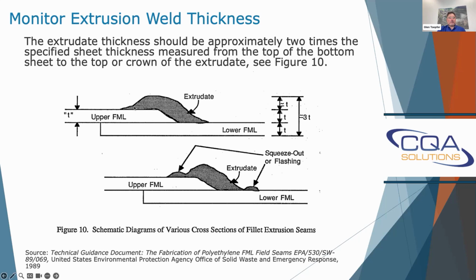A lot of times you get installers and they're lumping it up. They're making a high weld. And there are different studies that seem to be showing that that's not a good idea. That's resulting in the weld cooling at different rates and resulting in crystallization of the weld and a weak weld ultimately.